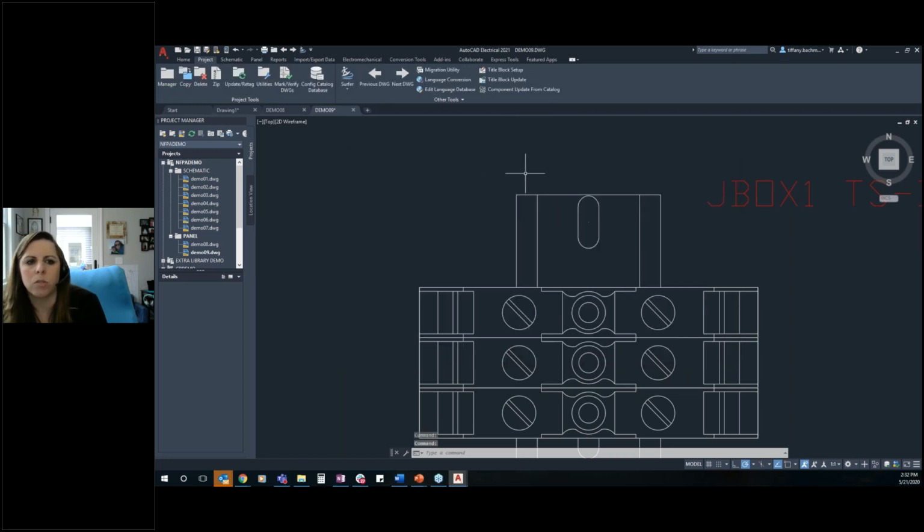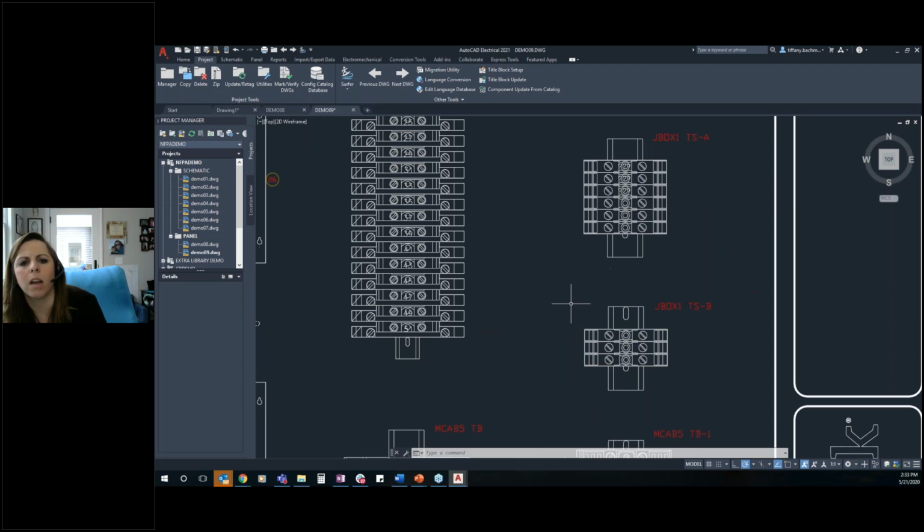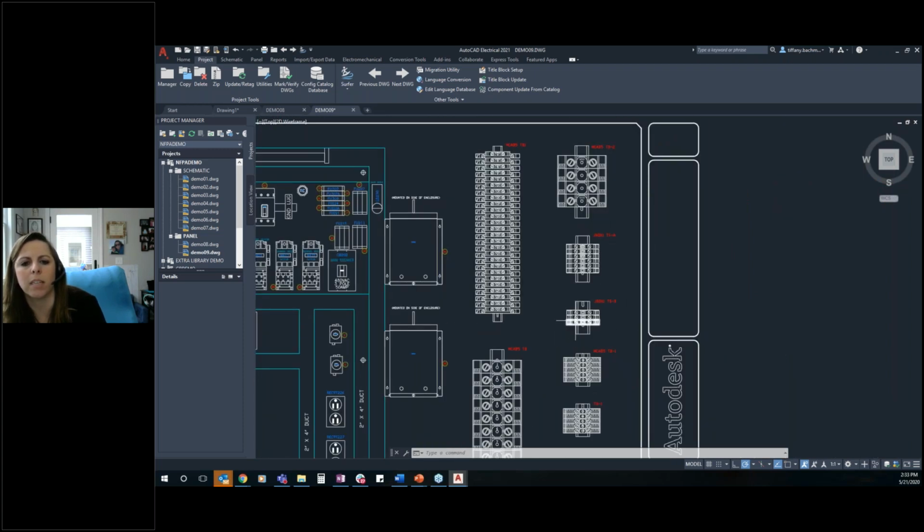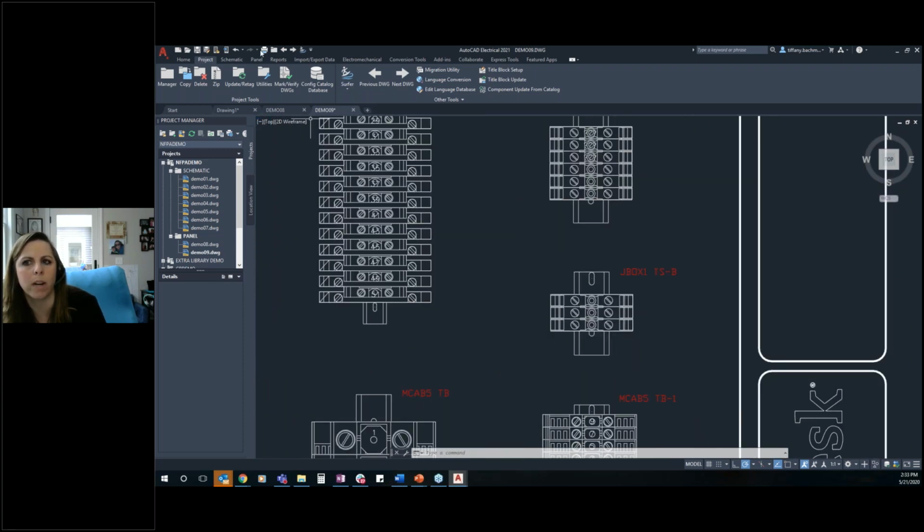So say there's a wire number mismatch between schematics and a footprint. The footprint says wire number 1, schematics say wire number 2. There's nothing besides going into the terminal, doing a full retag and then going into each terminal strip and telling it to rebuild. There's nothing in there that I can run a report that says, hey, I've detected some sort of mismatch information. I guess that's what I'm trying to understand, I don't know what the full rebuild is. The project-wide update and retag will do it. You don't need to do a rebuild of the database, if that's what you're talking about with the rebuilds.